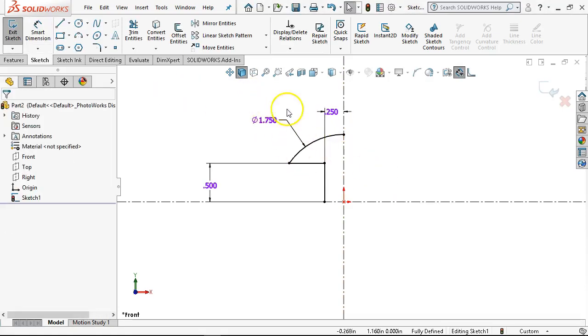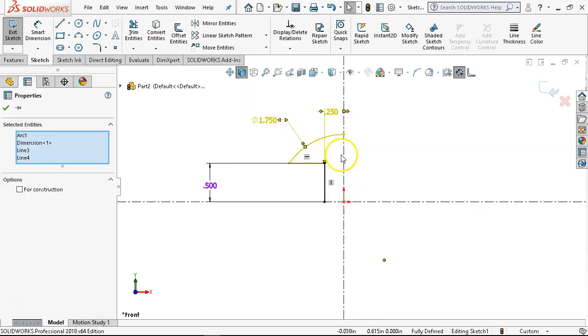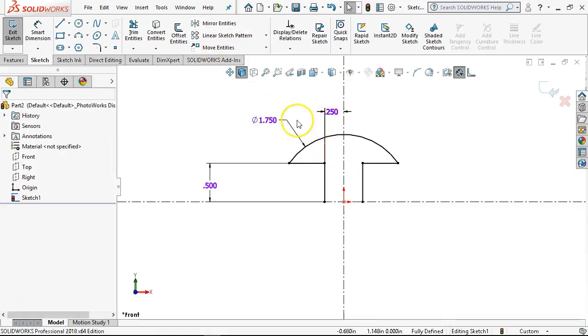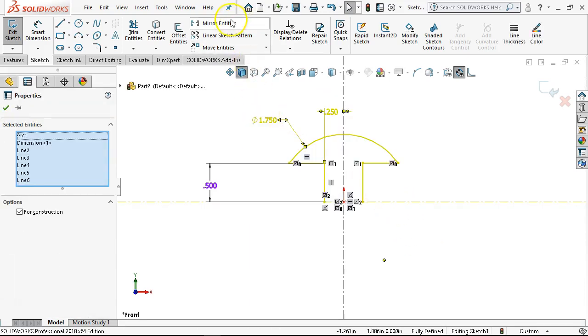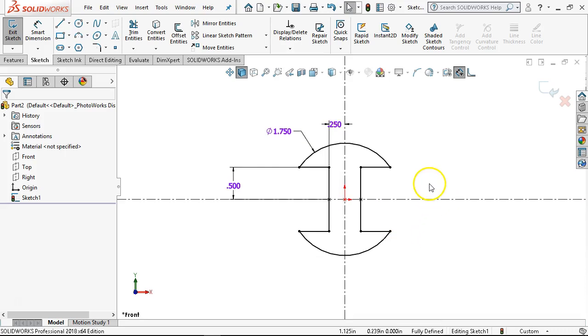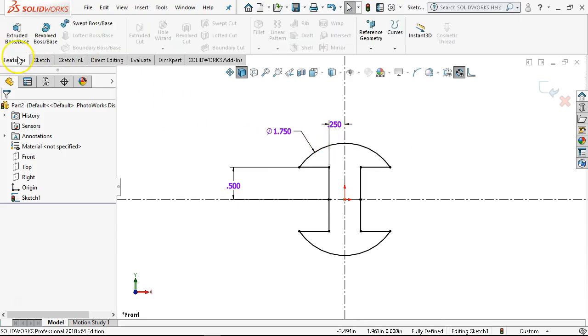All right. We're going to mirror in one direction first, so I'm going to window pick, control select the center line I want to mirror across, and that gives me my geometry. And it didn't put the points at the top of the arc, it just made it a complete arc, but it did put the points at the line, showing me that that was the mirror, that was where the symmetry was at. Because of that notch in the middle, I am going to go mid-plane.